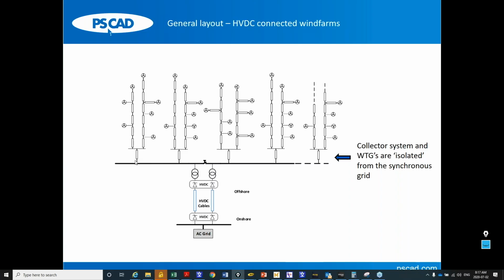If a feeder trips, these wind turbines get isolated from any external connection. They're just connected to a system of cables, right? So if the wind farm controls don't react to this condition correctly, there is a risk of severe sustained overvoltages in this part of the isolated feeder, which could seriously impact and damage equipment. So these are some of the items that you study with PSCAD.